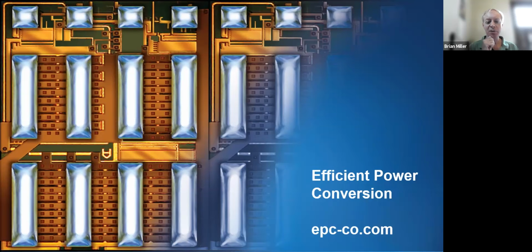Now with the switch node in the middle, yes, you could have some added inductance. Adding inductance typically isn't a problem, because a lot of times that node is in series with an inductor. So adding inductance in series with an inductor isn't too bad and might actually help act like a little bead. Capacitance, yeah, that's not good. You don't want to add a lot of capacitance from the switch node to say ground. But with layout, with separating the planes by enough, it's a design trade-off. I guess that's the best I could say.